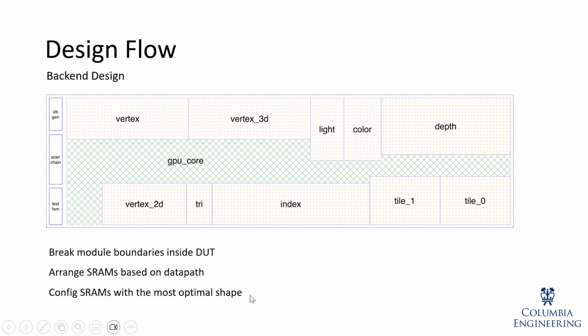The second improvement is the shape of the SRAMs, which is decided by the number of muxes in the SRAMs. We tuned a few times to get the best shape for every SRAM in order to have an optimized space for the other logic and routing. And of course, we also did some parameter tuning for further optimization.